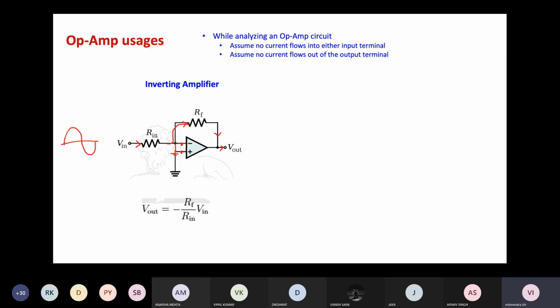Yeah, you are right. This circuit is very simple. So what the op-amp is doing is, yeah, I guess you are not getting that subtle point. You can say that we can just take the output across RF, and we can ground this and take the output across the RF. Is that what you're saying? No, sir, I was asking that you said that in an op-amp there is a very high gain, but here there is no function of the op-amp, only the choice of resistors. Yeah, so we are not using the internal gain of the op-amp in this circuit.